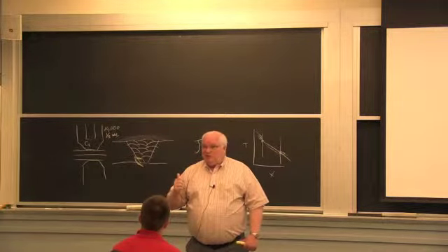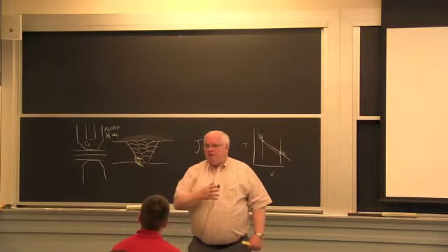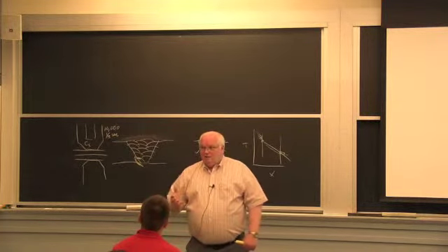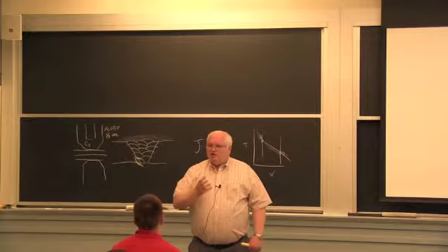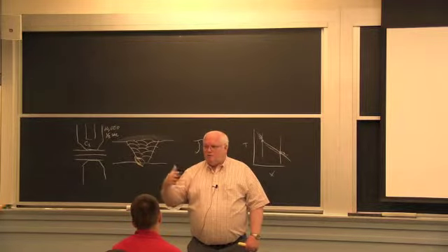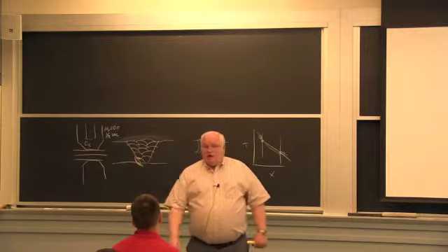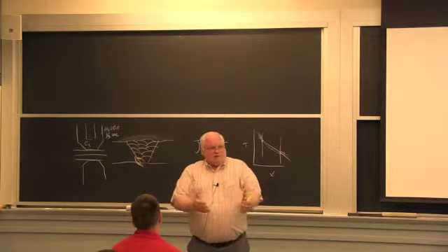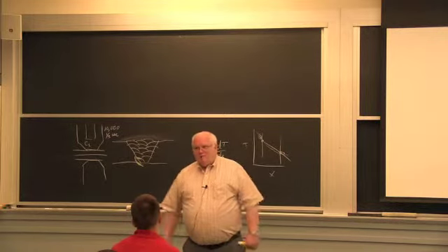100 welds, that's like 10 minutes. You're going to shut down an automotive line, which is turning out 1 car a minute, okay? $5,000, $10,000 profit a minute. Every minute you shut down is lost profit. So they wanted something where they only had to change the tips during the scheduled shutdown, which was like halfway through the shift, okay? That was 2,000 welds. So Ford had a spec of 2,000 welds. When they first started using galvanized steel, they were getting 100 or 200 welds before the tips were worn out. And that's why I said you've got to put 3,000 spot welds in the average automobile, because you need 2,000 good ones. They were making a lot of bad ones, okay?